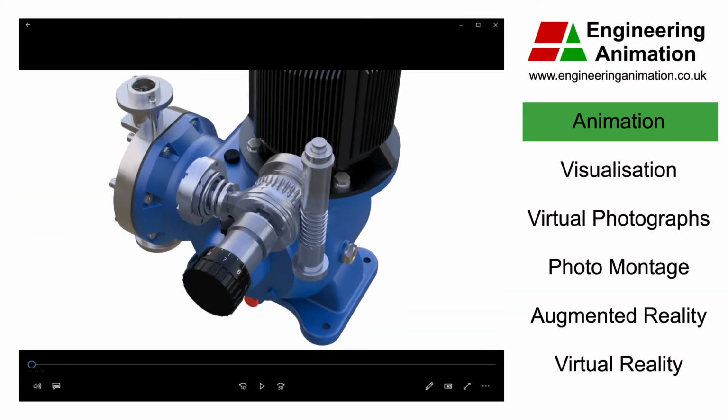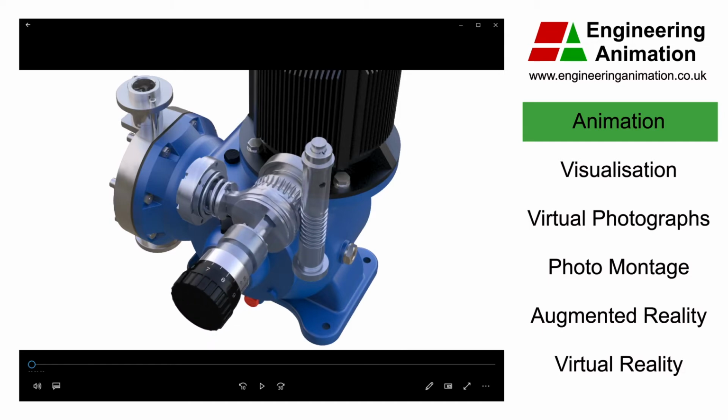Here, we reveal the mechanism of a reciprocating dosing pump with a variable stroke. As you rotate the dial, the stroke increases and raises the flow. Rotate the opposite way and the stroke decreases. This is achieved by linking all the components together in a kinematic chain, so they respond just like the real machine. It's a vivid and engaging way to show something that would be difficult to describe.